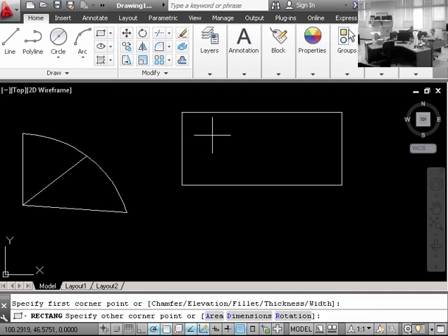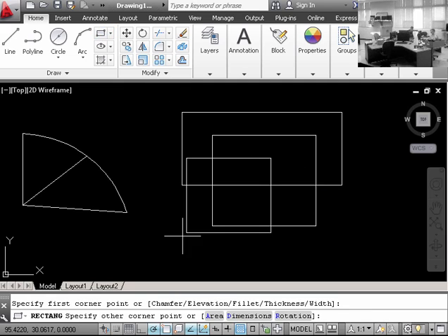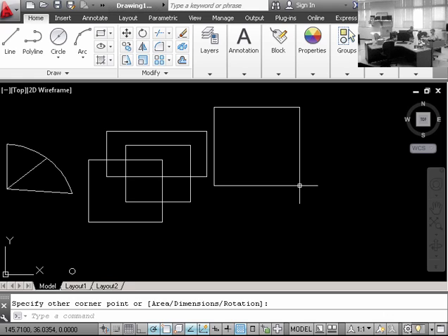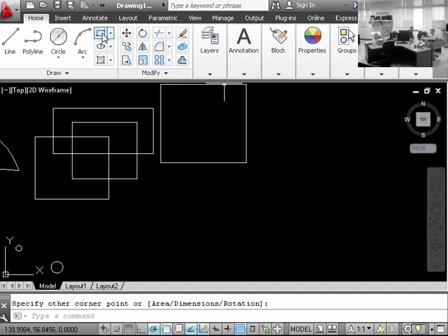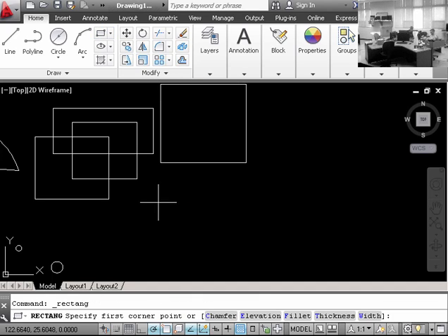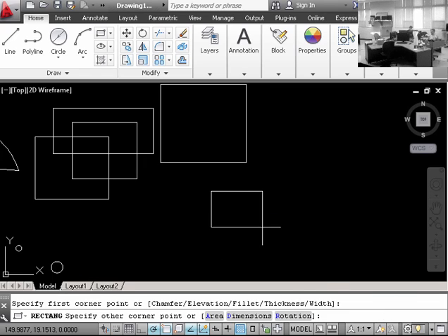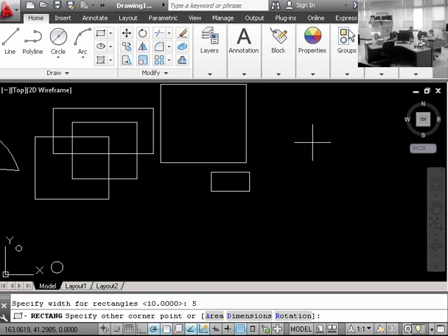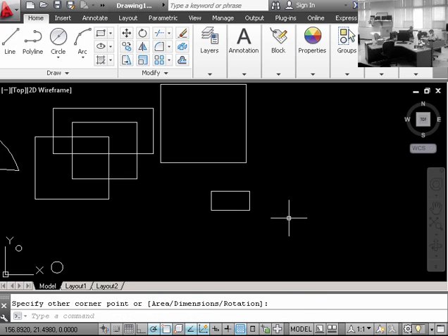It definitely speeds the process up, but you know that we don't just get to freehand everything we do, right? We always have to use dimensions. So if I want to do a rectangle with dimensions, I click the button, I look down at the bottom, it says specify corner point or other options. I'll give a start point, and I can actually enter in dimensions by choosing the option, see how there's little options right here? I can click on these buttons, or I can right click and say dimensions. And let's say I want our rectangle to be 10 horizontal, 5 vertical, and then one more click to select. So the actual rectangle command can make your rectangle real fast with just entering in some stuff.